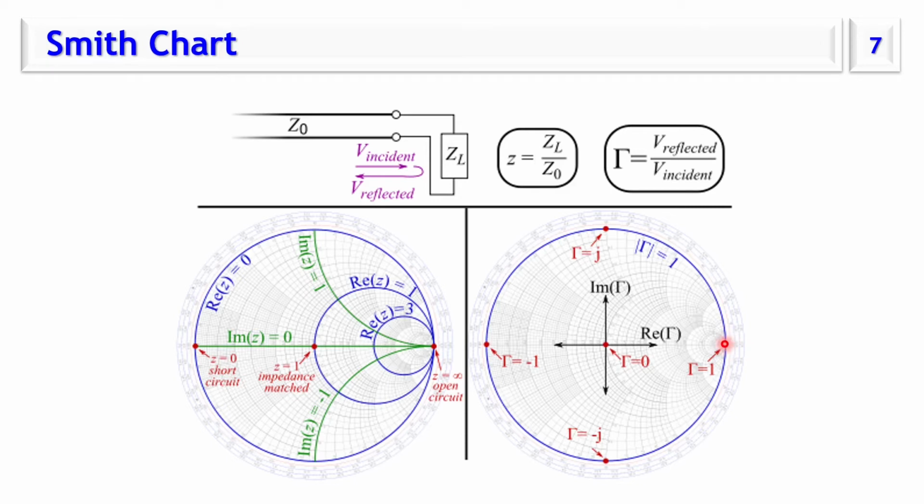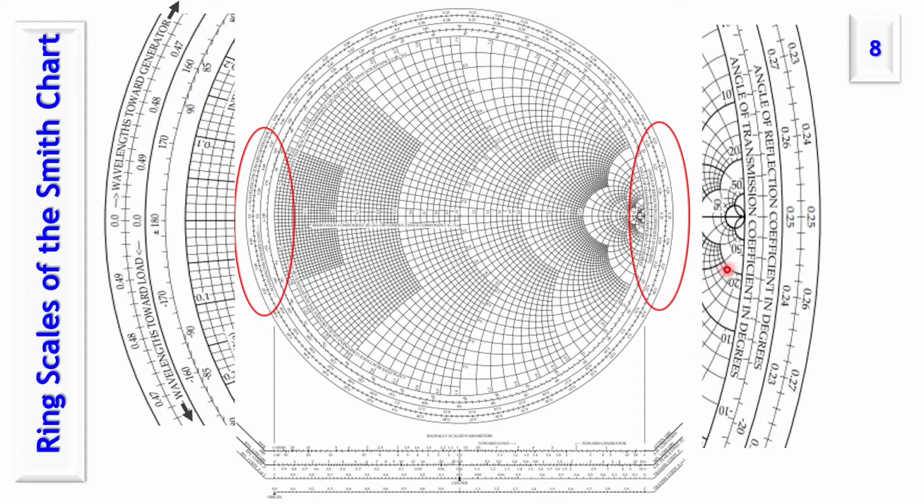And because the center for the reactance circle is on this line here, we don't draw the full circle, we just draw part of it. So those are arcs from the circles of constant reactance component of the load impedance.